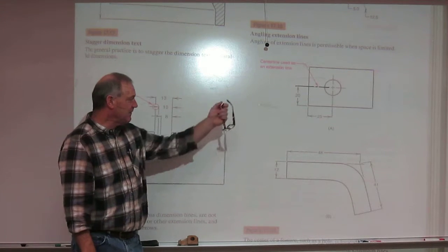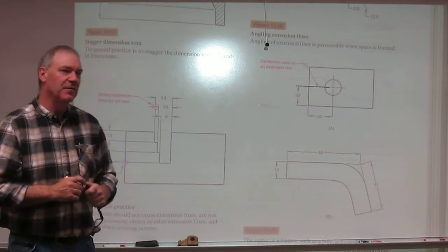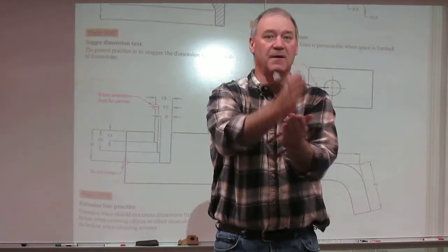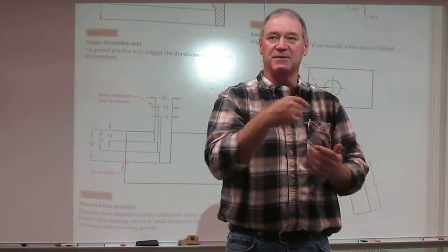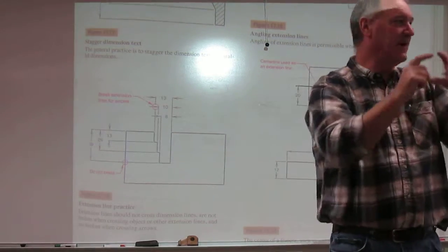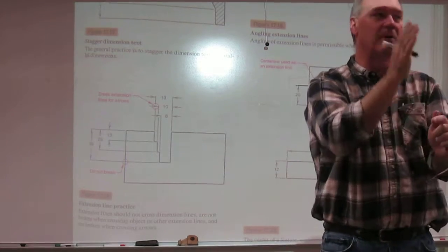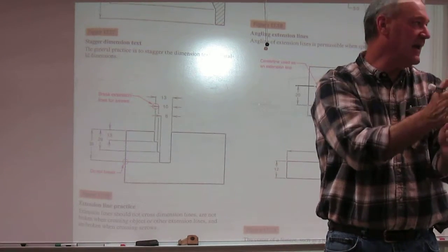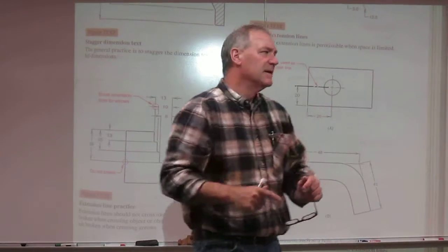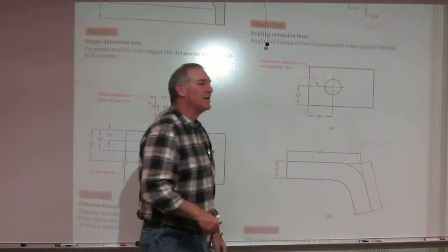There's really only two or three instances where I will do that, and that is mostly if I'm doing a pier deck and showing somebody I'm hitting the center of all these features. So I switch that to a center line, saying you're getting these centers, because I might have a small column at a large scale and I want to make sure they know I'm hitting the center of that thing versus an edge. That's about the only time I'll do it. For us right now, don't ever put it in the center line.